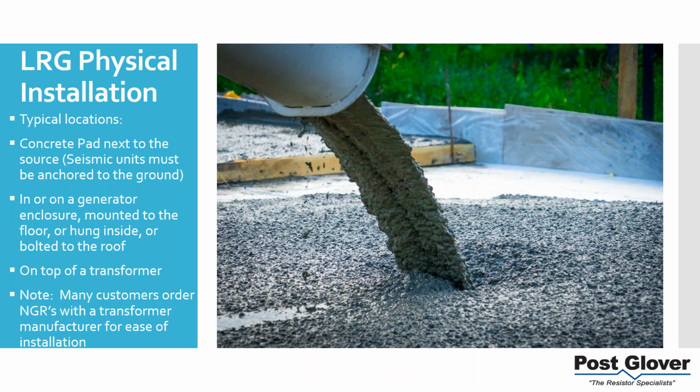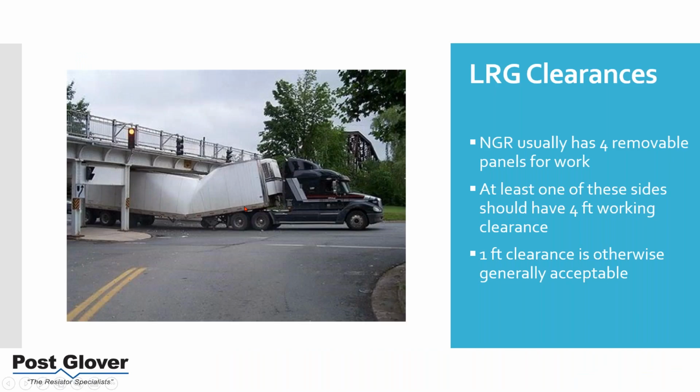One thing I'll say about that is just make sure that's true. A lot of times the transformer with the NGR on top is too tall or too big for shipment, and they ship them separate anyway. So in my experience, you're paying roughly double the price, and if you're not getting them installed, you're having to do installation anyway. That's just food for thought. Just make sure that you're actually getting what you think you're getting.